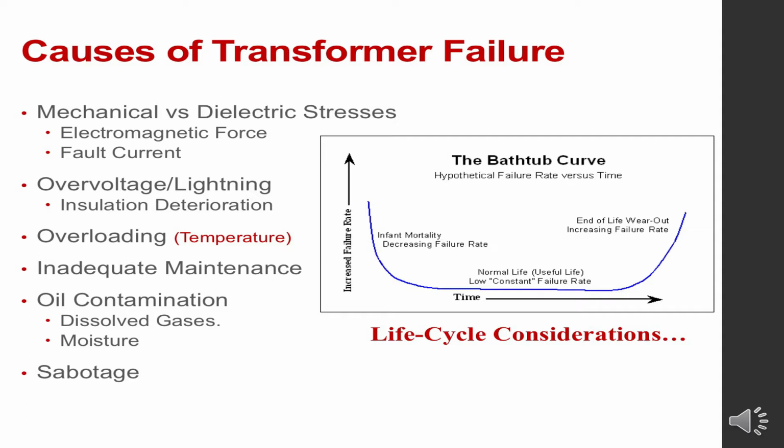On this first slide, I want to point you to the graphic on the right side of the slide, the so-called bathtub curve. What this is indicating is the failure rates of a system as a function of its life cycle, from when it's first put into service to when it's retired after service. You'll notice that the curve is concave, and that there are two primary times when failure rates are highest. The first is what they call the infant mortality rate, which means when we first put something into service. And the other spike in the failure rates is at the end of the life cycle, when the system is about ready to be retired.